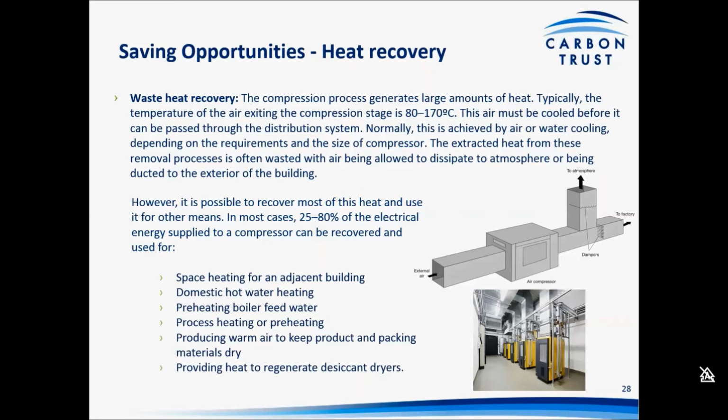For the higher temperature machines, you see the picture at the bottom there. Those are machines that have been water cooled. So there's a use for the warm water. Very often you would use it to preheat boiler feed water. I've seen them used to generate the vast majority of CIP water requirements in the food industry as well. So big opportunities there, and taken at its simplest, it's quite a cost-effective project to look at.